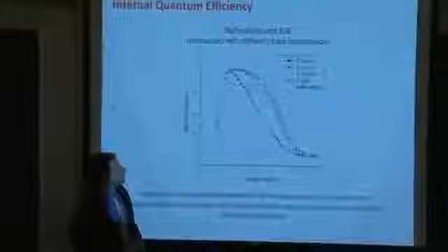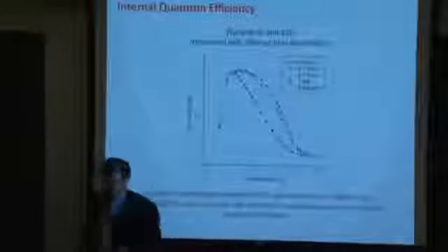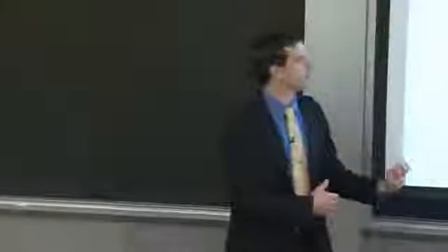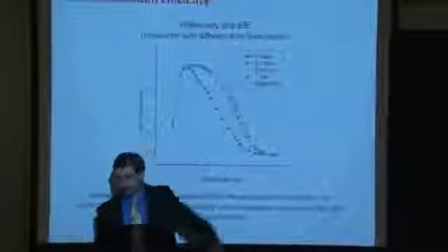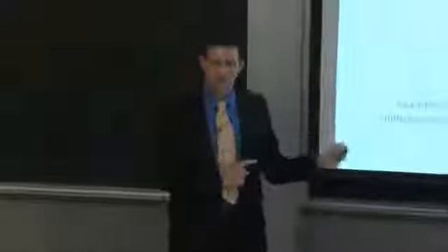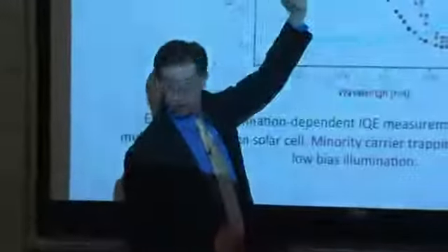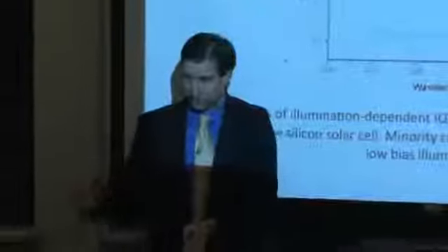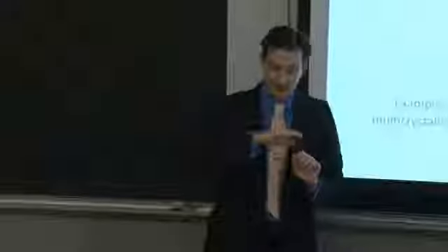And obviously you can't measure a quantum efficiency without having some light involved. And so the light that was being generated by the monochromator was much lower in intensity than these illumination intensities here. And so it was more of a perturbation on top of a steady state background. And we ran the measurement in exactly those conditions. We had a steady state background light, and then we chopped the monochromator light coming in and used a lock-in amplifier to track that particular frequency. So we're able to detect the small perturbation due to the monochromatic light coming in on top of the steady background.